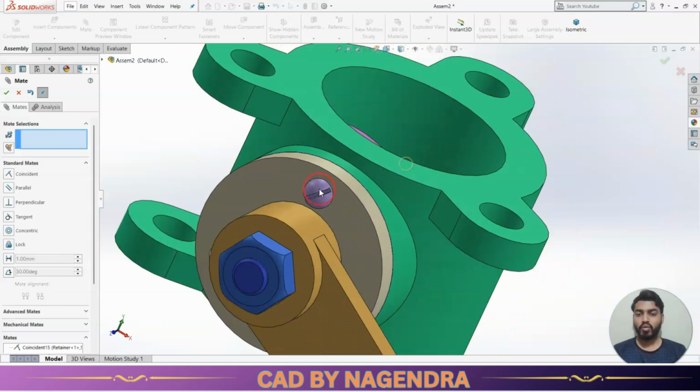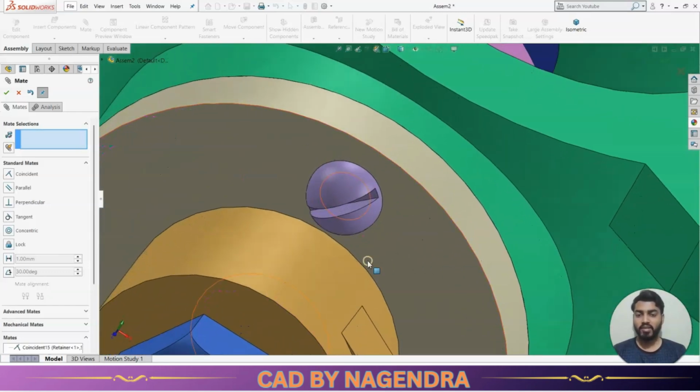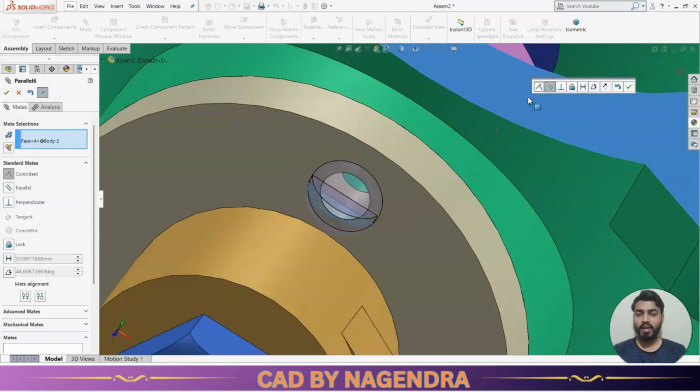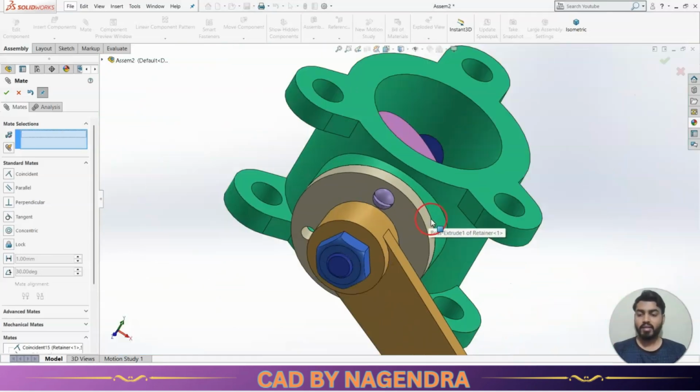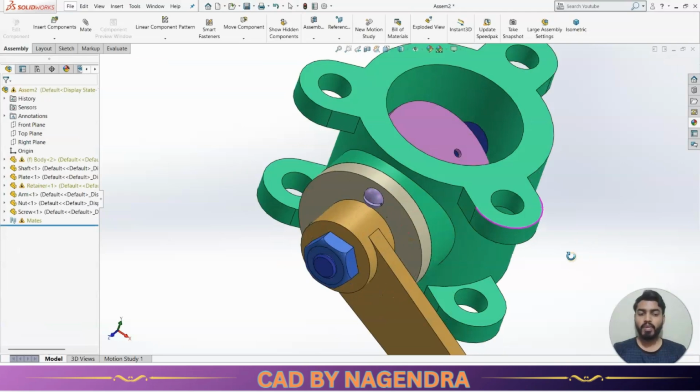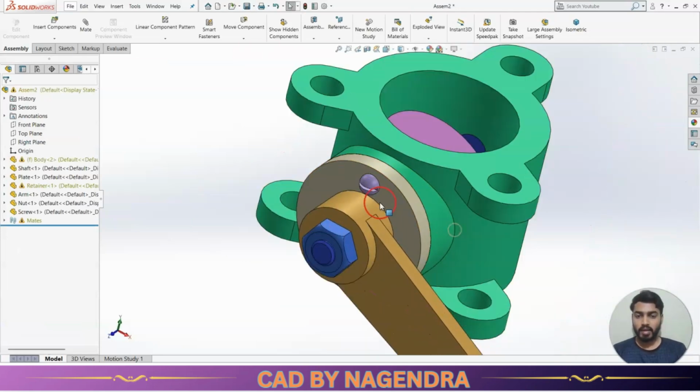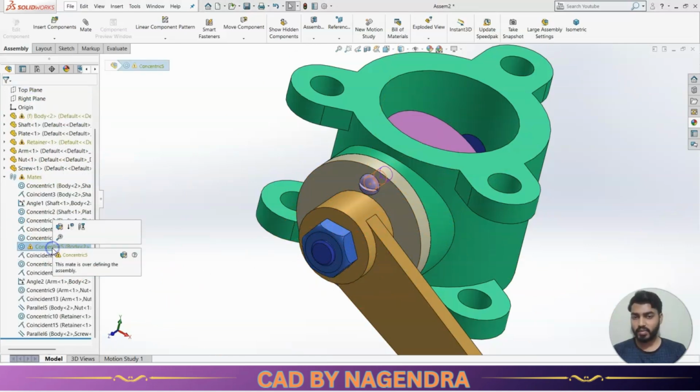Okay. Then to lock this rotation, here also we have a flat face. This face to this face, I'll make it parallel like this. Then no rotation will be present for that. Then directly we can create one circular pattern. Again you can see an error is there. So some extra relation is highlighting here. Let me go back.